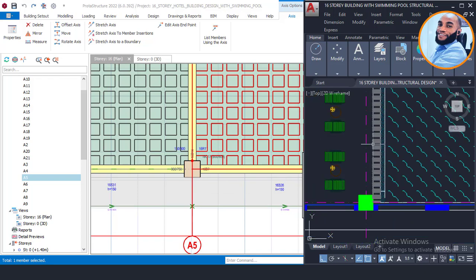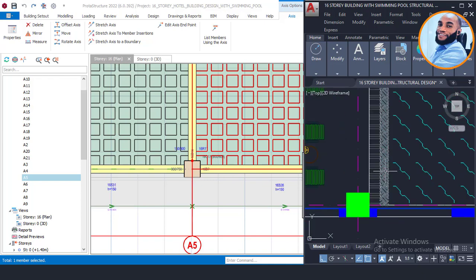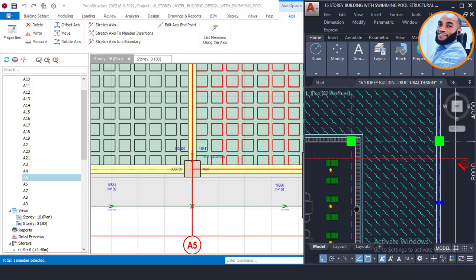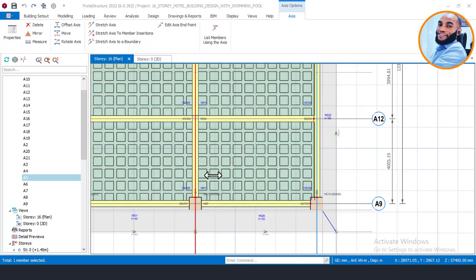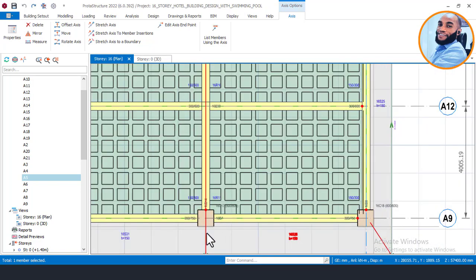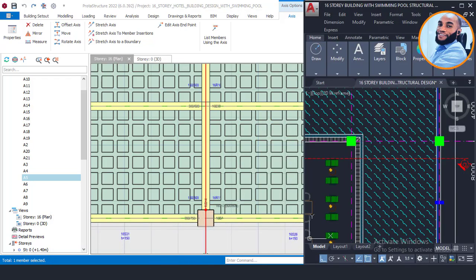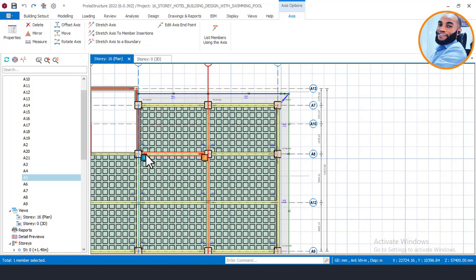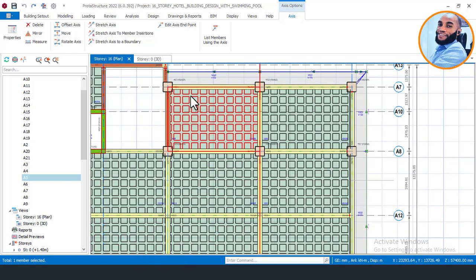So I would say that, as a structural engineer or as a civil engineer, you have the right to shift this retaining wall backward just for the safety of the structure. So that's what we are going to do right now, shift this retaining wall backwards to align itself on this column and on this beam here, okay? So with that, I will not have to offset this backward again. I will have my retaining wall for this pool along this axis, on this place and on this place. It is only around this area here that I will now make my offset.